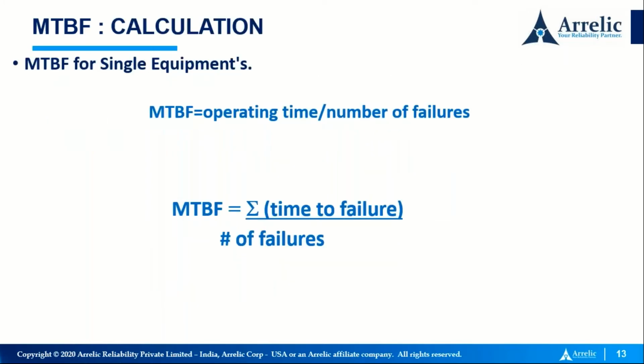So to calculate MTBF, it's the summation of the operating time over the number of failures. MTBF is the summation of time to failure over the number of failures.